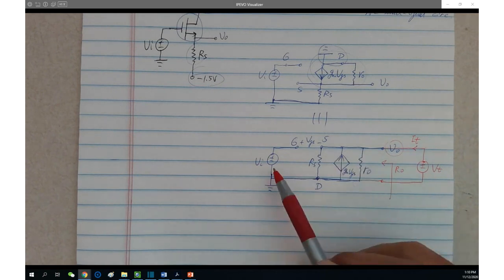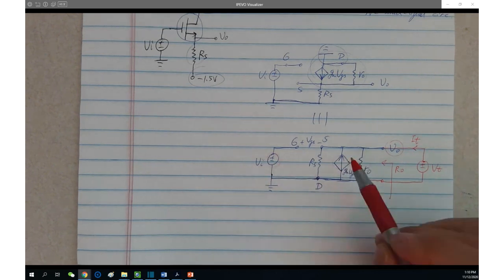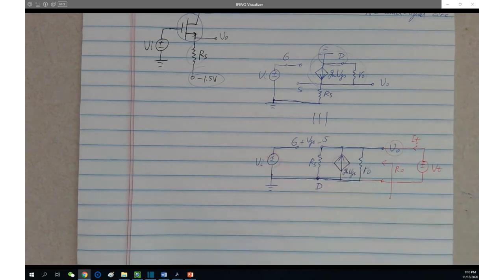Because in the circuit, we are seeing one independent source and one dependent source. To the dependent source, what's the principle? No matter what, you can't touch, remember? We always follow this. No matter what, you can't touch the dependent source. It is there forever. Superposition, the Thevenin, or now you're looking for the equivalent resistance. No matter what you are doing, you can't touch the dependent source. It is what it is.